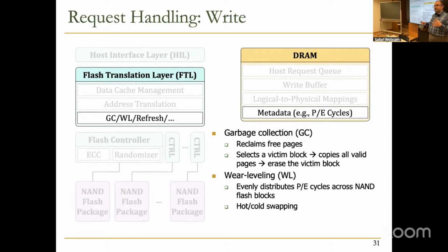So that's not a very intelligent solution, because at some point you cannot use your storage because the data is scattered on basically faulty pages and blocks in the flash memory. So there is a technique which we call wear leveling that tries to make sure that we don't have hot blocks and cold blocks. So hopefully we are going to write and do program erase evenly across all the blocks. So that's the job for wear leveling.